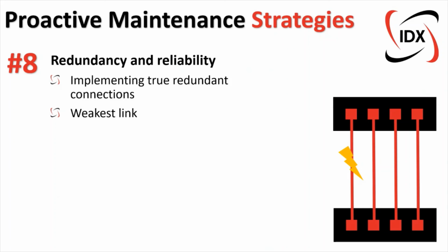There are often very useful technologies that can get integrated into PROFIBUS, such as fiber optics, implementing fiber rings, where an OLM has two ways to actually communicate between the different OLMs. So if one of your fiber links is broken or damaged in the field, it has a redundant path to maintain its communication. For copper, you can utilize things like a Y-link. Alternatively, use things like PROFIBUS, which also give you redundant cable runs. And then there are considerations around redundant PLCs and having a smart PLC switch to redundant devices, having two devices that can perform the same function quite quickly.